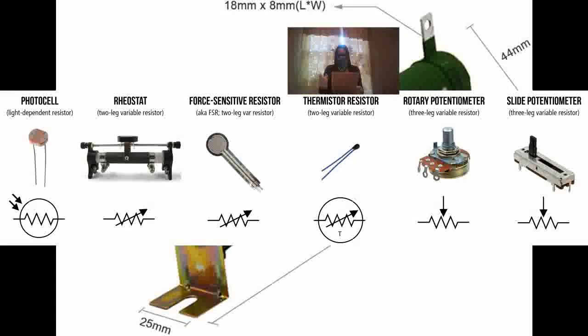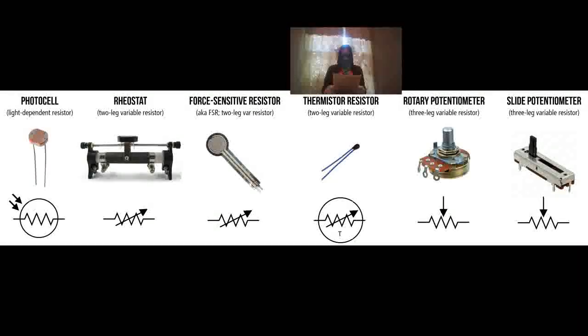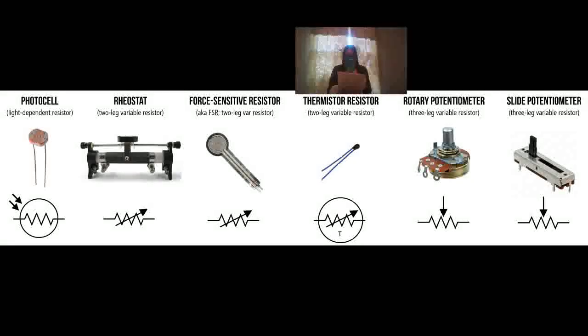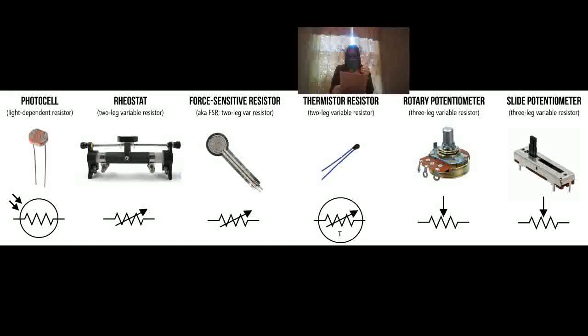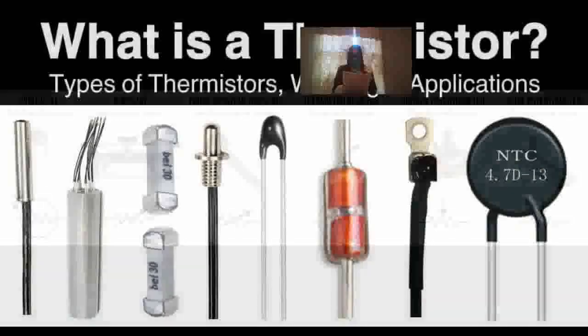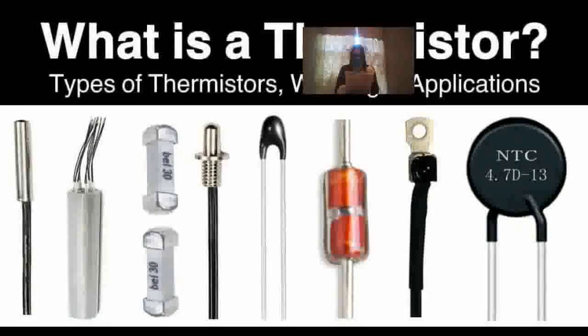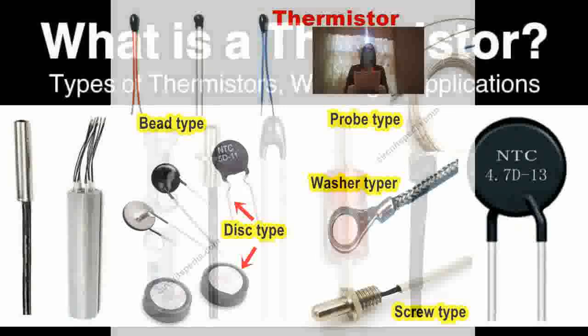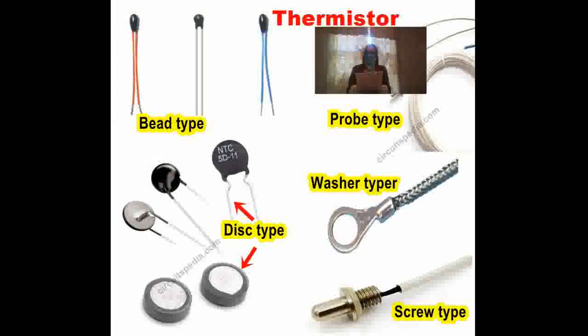Various styles of potentiometers are illustrated in figure 3-35. Also shown is the potentiometer's schematic symbol. Thermistors. A special type of resistor is called a thermistor. In comparison to other types of resistors, a thermistor is unusual due to its ability to change resistance value rapidly as its temperature changes. It is commonly used to prevent high inrush currents in electrical circuits.